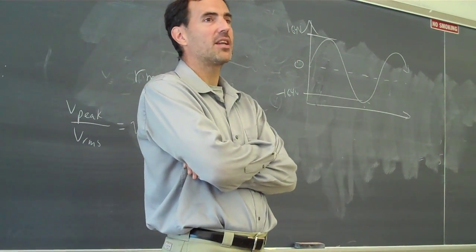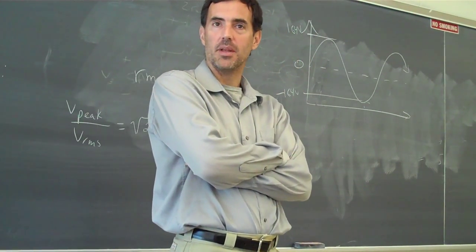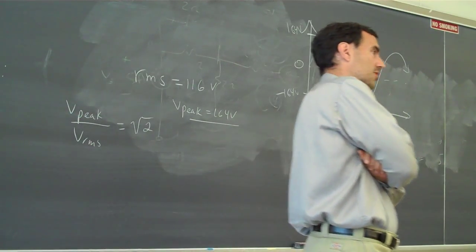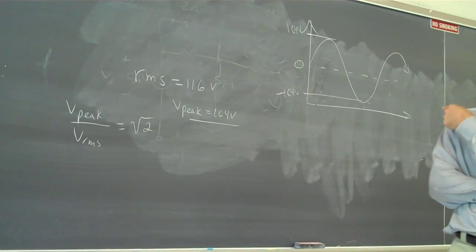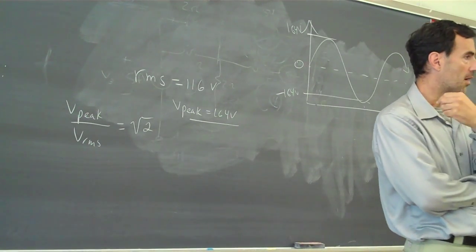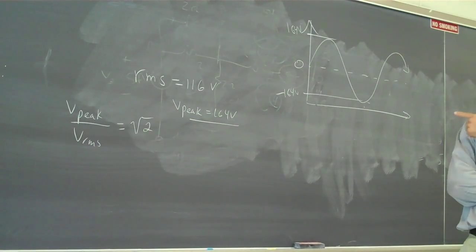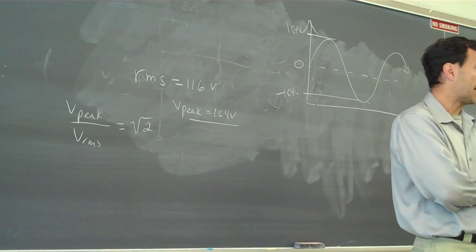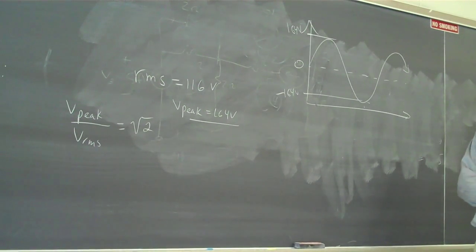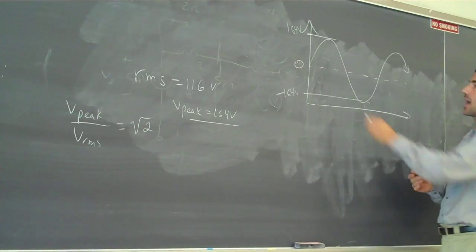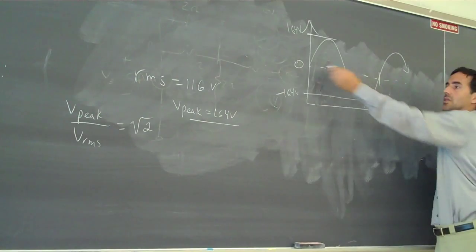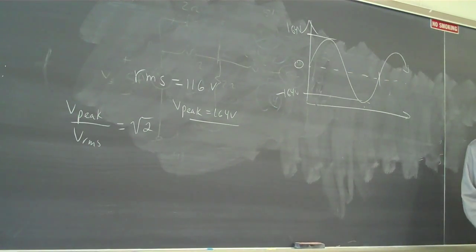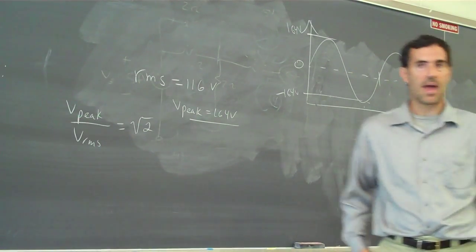So that means the greatest voltage we can read with our equipment is 5 times 4 blocks, around 20 volts. So our oscilloscope is not designed to be able to read this voltage coming from the wall. So we won't be able to do this experiment with our equipment. But if we did measure it with an oscilloscope, we'd get this signal. I haven't quite finished here. I've got the vertical axes labeled, but let's see if we can label the horizontal and see what settings I should use to get that.